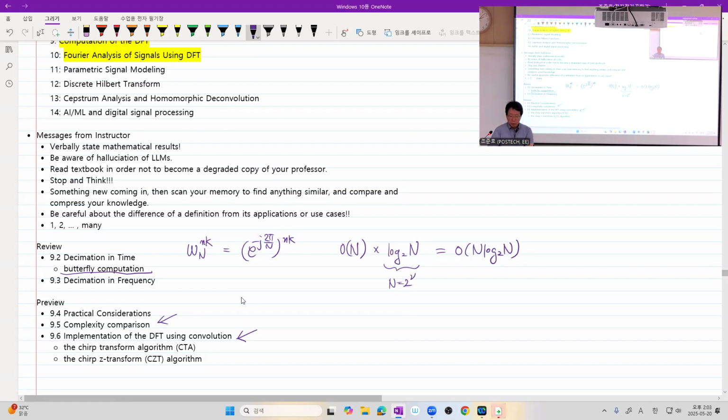But the importance of this algorithm, the chirp transformation algorithm or chirp Z transform, increases, especially in digital communications, where we consider so-called high mobility, which means high Doppler shift, Doppler frequency shift environment, where we need to estimate not only the delay and complex gain of each multipath in digital communications, but also we need to know the velocity or speed, or equivalently the Doppler frequency shift amount of each path to correctly estimate the channel and also compensate for the effect of that